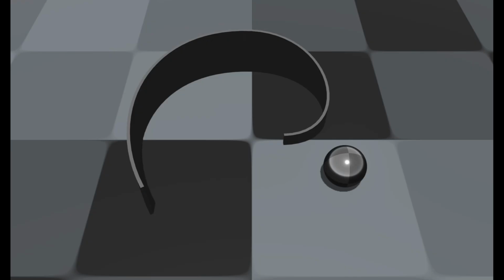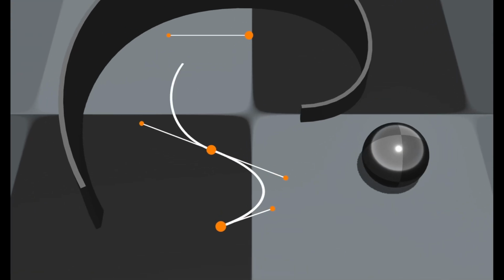The wire variant of ball guides are also easy, although funky math is used to get the ends to bend down and terminate nicely. Again, I use the path and sample the points, but this time I will make the points keep track of the direction it's going by getting the tangent of the path. To get the wire to end into the ground, additional points at each end of the path are added.